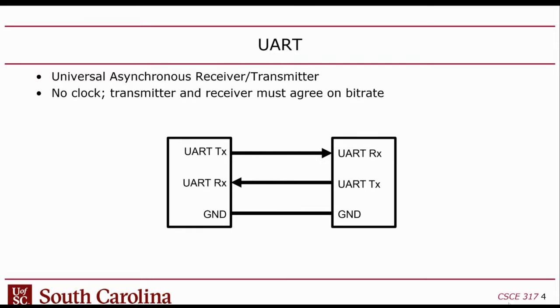Unfortunately, you can't get away from that. You have to have a common ground if you're going to do electrical. You have to have a reference, unless you use differential channels. But these are single-ended channels, just to be clear. So there's 1 bit per wire. There's a ground, and these wires are relative to the ground.